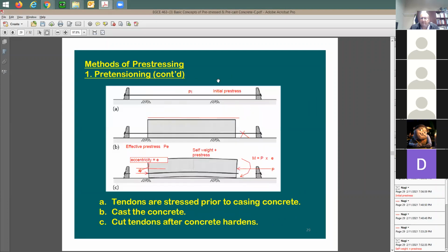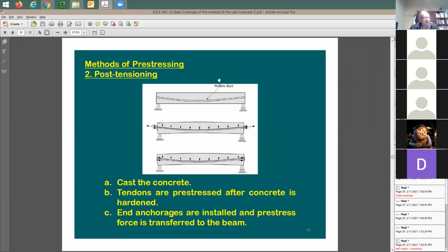Usually when you have a yard or a factory, you do it in the field. But in some cases, you have precast members with some conventional reinforcement, like non-pre-tension reinforcement, the regular rebars, and they do it in the factory, and then you take it to the construction site, and then you put the tension to it. You're gonna see this usually in bridges.